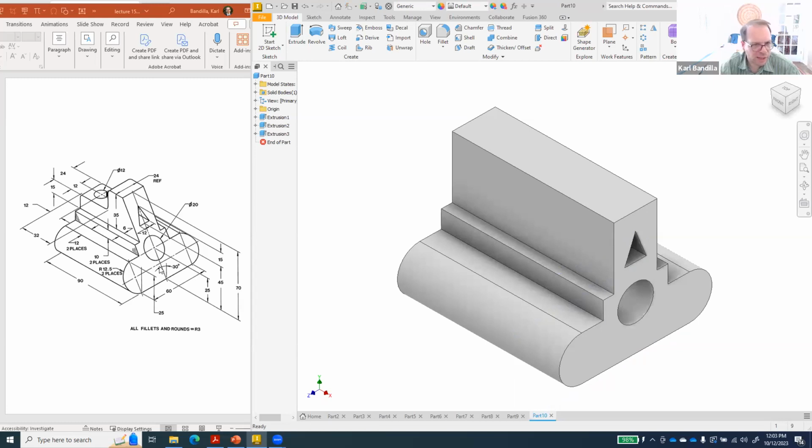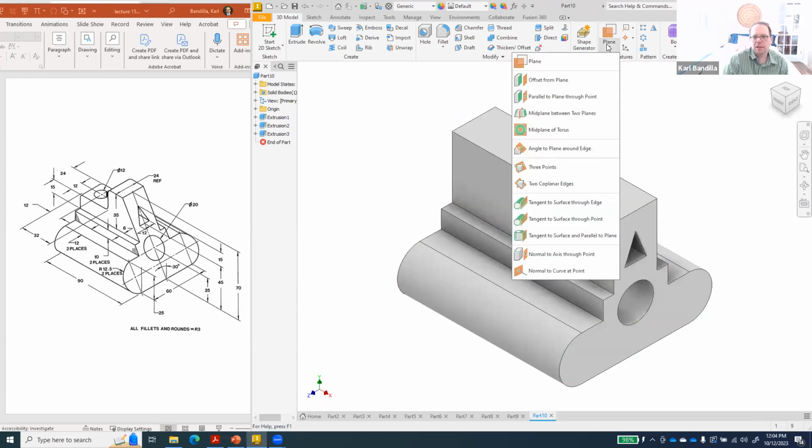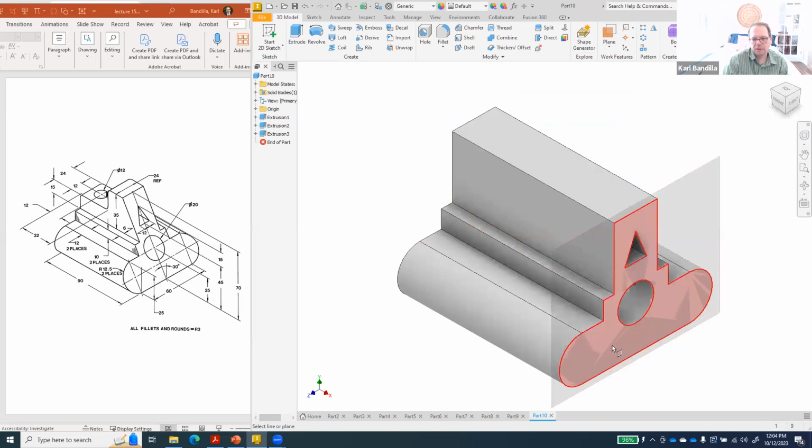And I was looking at this figure, but can't see anywhere where it says that this hole does not go all the way through. Right? If this was not going through, there would have to be some kind of note saying it doesn't go through, but there isn't any. All right, so what we'll do is we'll create this cut. The way we'll do it again is we'll create ourselves a work plane, and then we'll cut everything down to the work plane. So plane, we need an angled plane because we're giving the angle. We want to have this plane going around that angle.